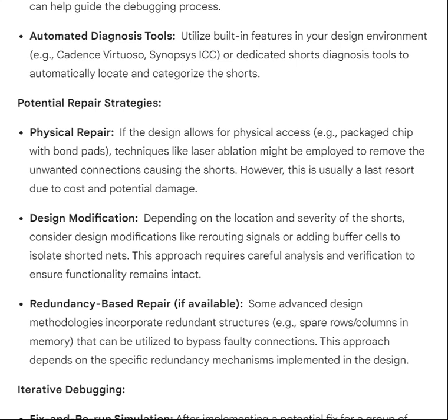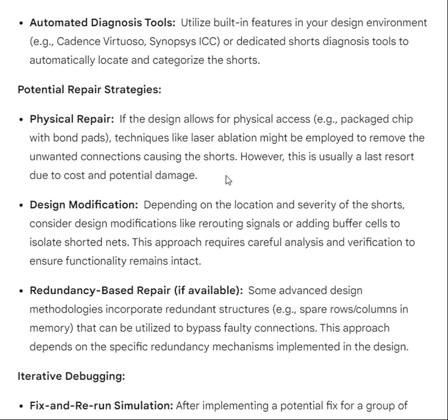Potential repair strategies. Physical repair. If the design allows for physical access, e.g., packaged chip with bond pads, techniques like laser ablation might be employed to remove the unwanted connections causing the shorts. However, this is usually a last resort due to cost and potential damage.